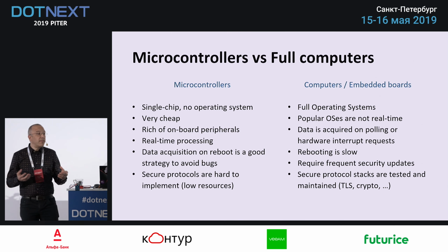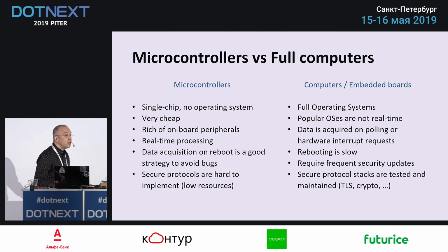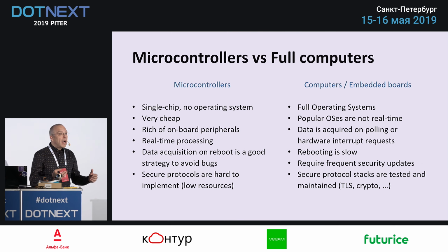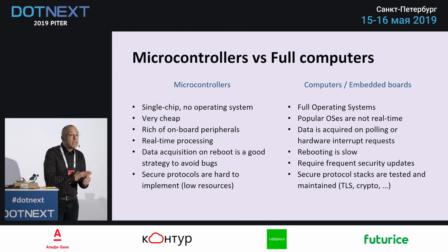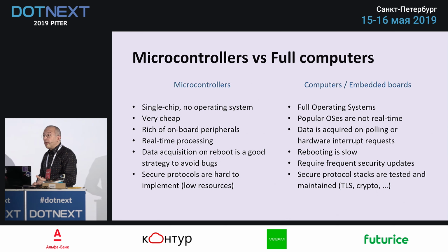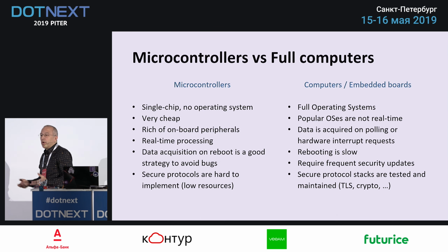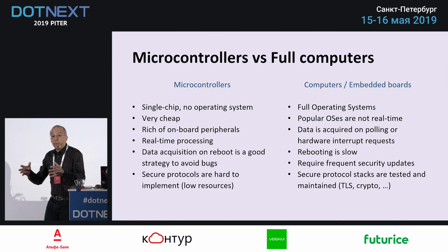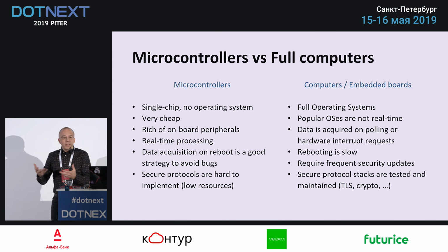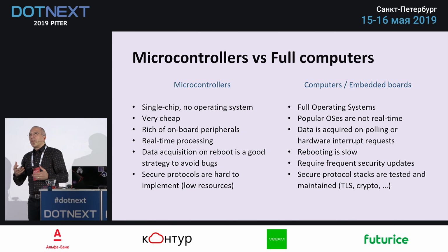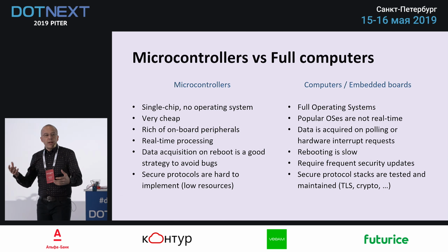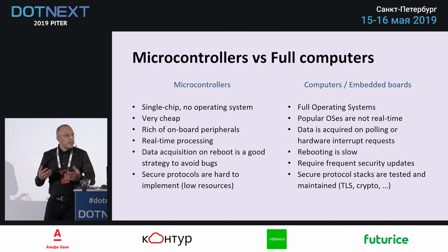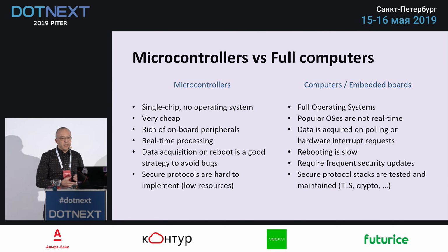If you need real-time communication, either you go to a real-time operating system, which is pretty hard to use, or you simply use an Arduino, let's say, or other similar components like a microcontroller where you have the full power and you run synchronous code. Well, not really synchronous, because you also have interrupts, so you can deal with a certain amount of asynchronicity.